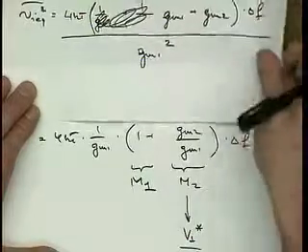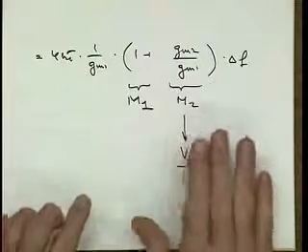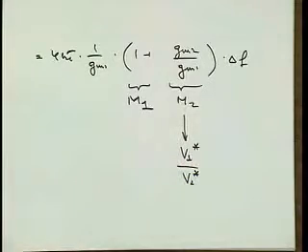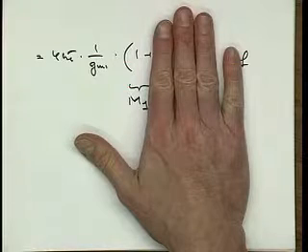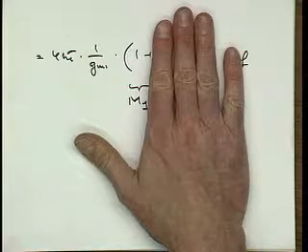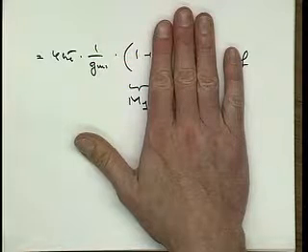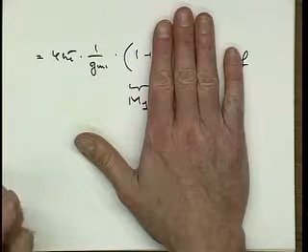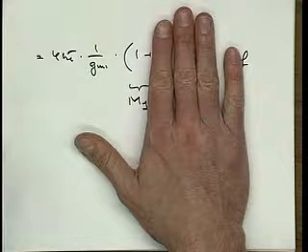From that we can conclude that in such a transconductance amplifier, at least for the simple one, and we'll see that this turns out to be true even for a more complicated one, we get noise from the transconductor. Sure, we build an amplifier, so we should expect noise from that amplifier. There is no noise vacuum that takes it away. And then we put other junk there, like this slope. Very useful, but it's going to add extra noise.